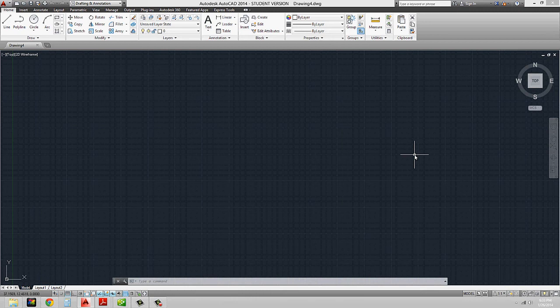Keep in mind that we shouldn't be adding things that are not really settings. For example, yes, I can save a drawing here, and I can work with objects and have lines and everything like that, and I can save it as a template. However, if I do, every time I open up a new drawing using that template, it's going to show up. So typically with different types of templates, it's very selective if there's anything in model space whatsoever. And typically there's not anything in model space.